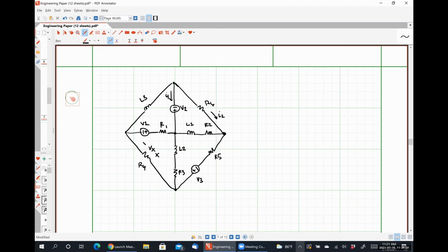So what is troubling you? Let's start there. Well, because of the inductors, when you're doing the circuit analysis, they would just be short circuited, right? Absolutely right. This is a DC circuit, so literally all of our inductors will be shorts. So we can erase them and replace them with a wire.